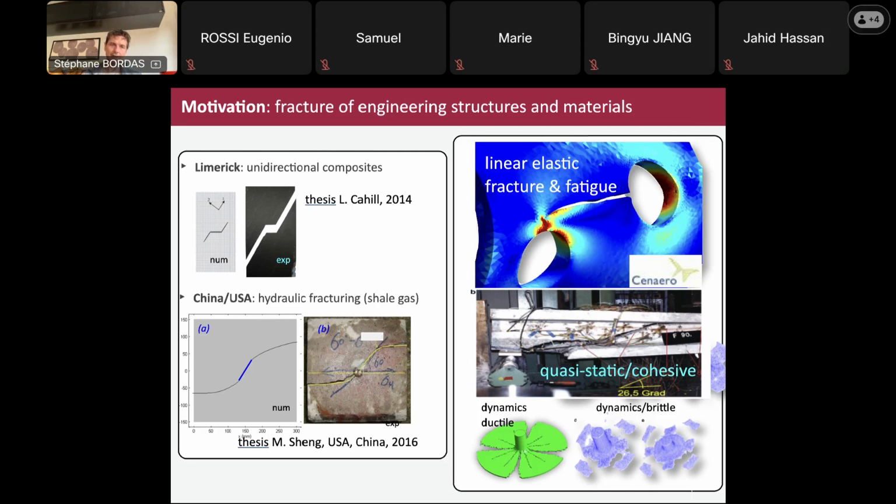And as you can see, the crack, instead of running horizontal as it should normally do, because you're pulling vertically on that sheet, the crack is running at a 45-degree angle from both tips, which are the ends of that crack that I'm showing now with the mouse. So the tips of the crack are originally here, and the cracks run along the fiber direction, simply because it's the easiest way that they can propagate. So on the left, you have the numerical solution. On the right, you have the experimental solution.